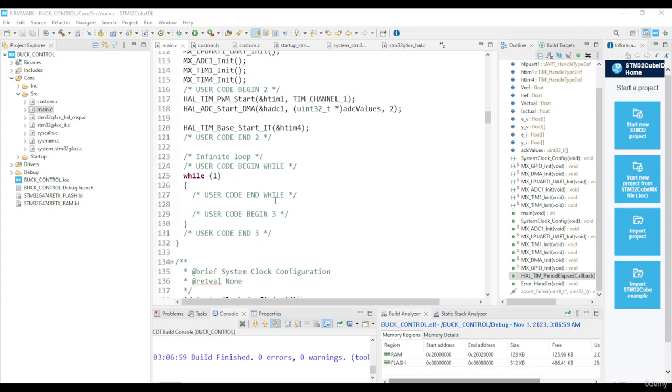If you want to limit the current, you essentially have to either use the duty cycle method where you sort of keep fingers crossed in a way, or literally have another if statement to say if this is above this, reduce the duty cycle as follows, as opposed to double loop control where inherently it just limits the current by default, as long as your ADC works, of course.